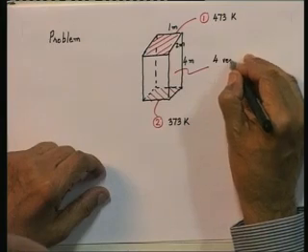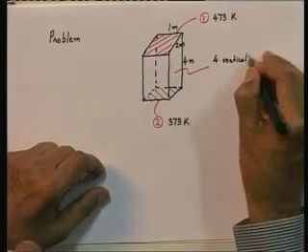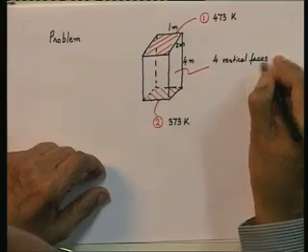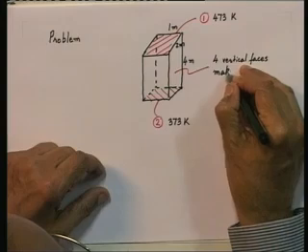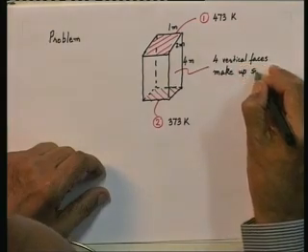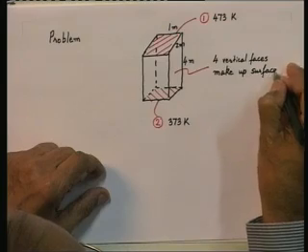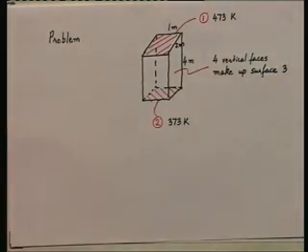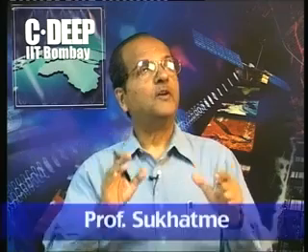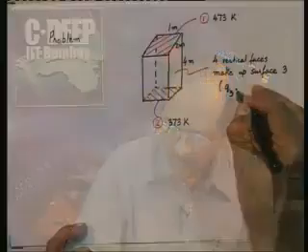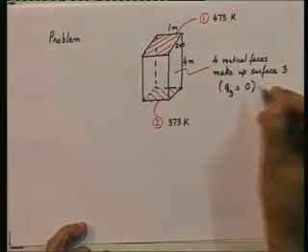That is a 3 surface enclosure now, because we are specifying the top horizontal face is surface 1, the bottom horizontal face is surface 2, and all the 4 faces together which are vertical make up what we call a surface 3, and that is perfectly insulated. Therefore, for those 4 faces Q 3 is equal to 0, perfectly insulated surface.